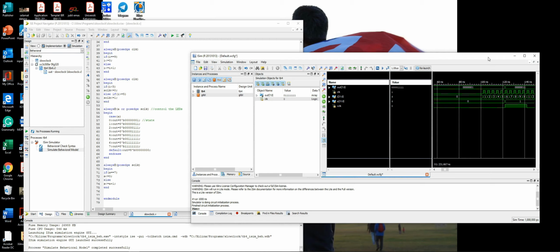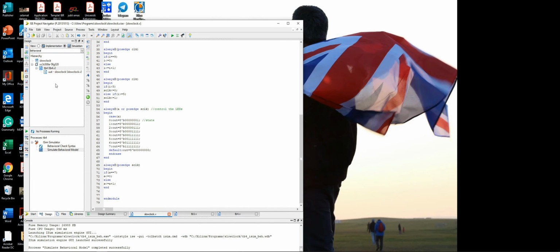Next, I'm going to upload for the project. What can we assign here? Actually, we can assign another file where you can do the mapping of the LED from the port here to the physical port on the board. I'm going to show you next, and try to have a look first at this coding. Then maybe I can show you how we do the mapping, the user constraint file, on the data sheet that we have, where they already provide all the pin numbers, so we can assign a pin number to each one of the LEDs that we assign here as the output.